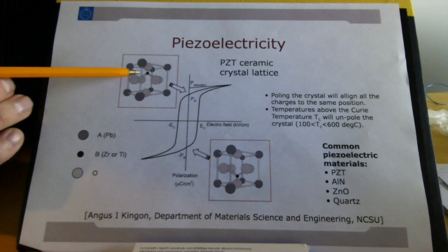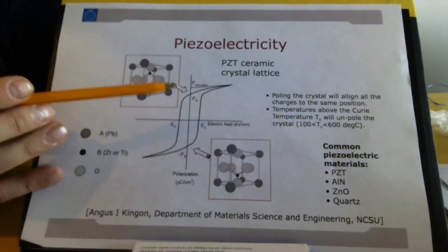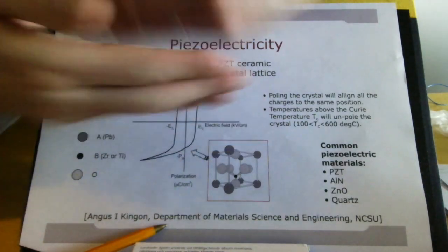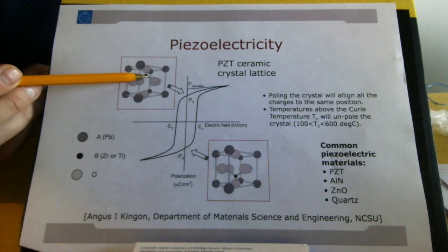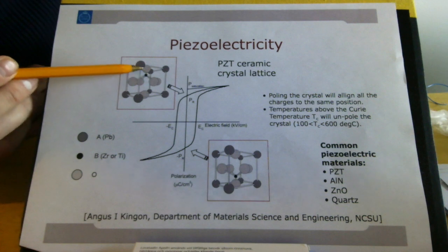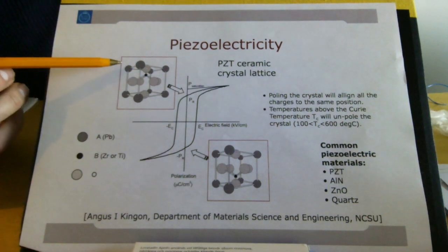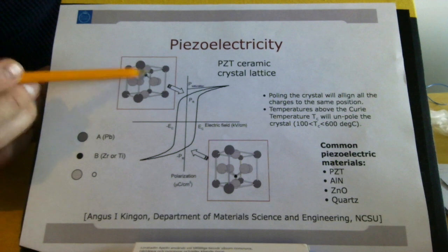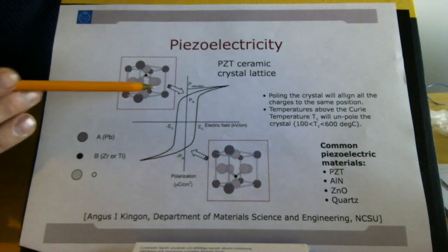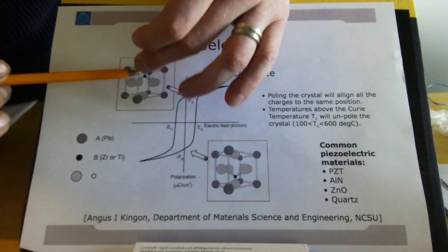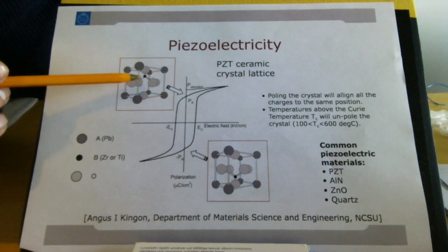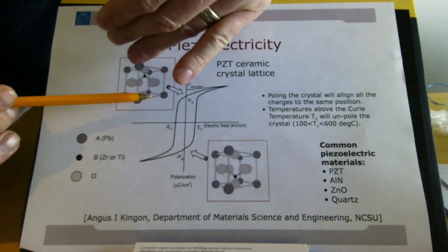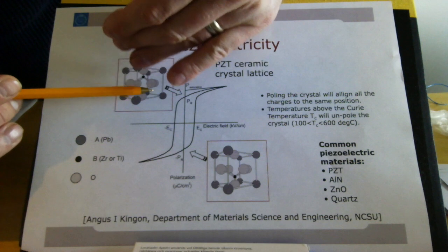So what's going to happen is, if I compress this crystal like this, then I will deform the crystal and I will move this little black atom a little bit either to the middle or to the top. And so you get an electronic redistribution. There's, of course, a certain distribution function of the electrons between these atoms, and I will disturb that distribution. So the electrons in here are slightly redistributed, and that will cause me to create, over every small lattice part, a certain net electrical field.